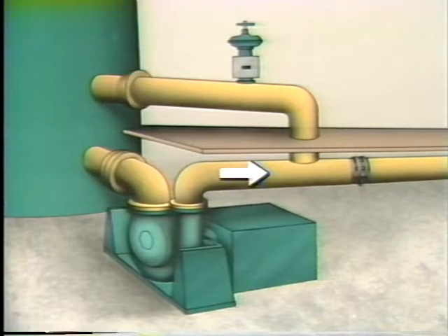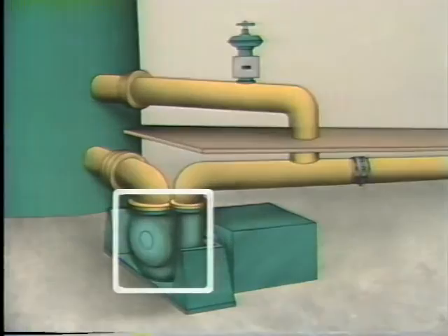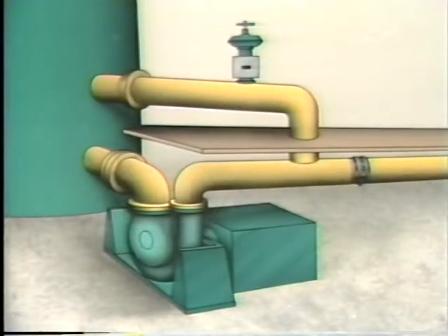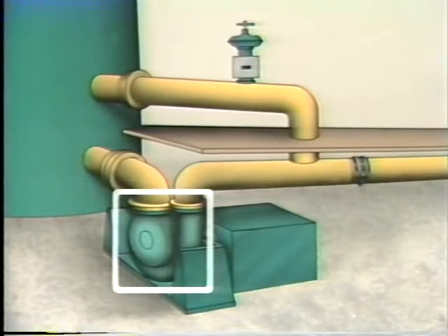If the plant demand for condensate changes, flow through the discharge pipe changes, and flow through the pump changes. Now, the variable that has to be maintained in this process is flow through the pump. Flow through the pump has to be kept above a given value to keep the pump from overheating.